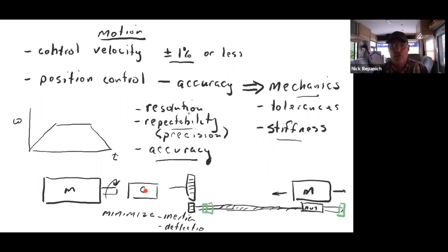You will see direct drive motors, they call them, or hub drive motors, where a linear motor might be out here. Instead of all this translation, don't do all that. Don't use a rotary motor. Let's just put a linear motor right here, and then we'll have direct motion. And we get rid of all those things that cause deflection and inaccuracy. What's the problem with generally doing that?